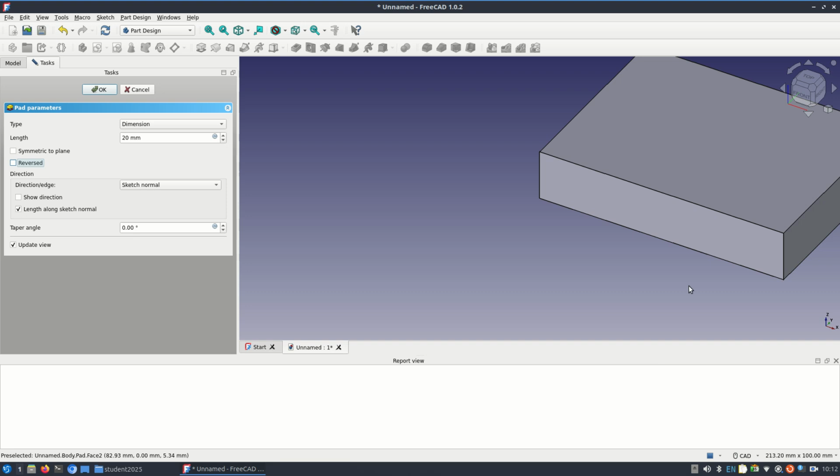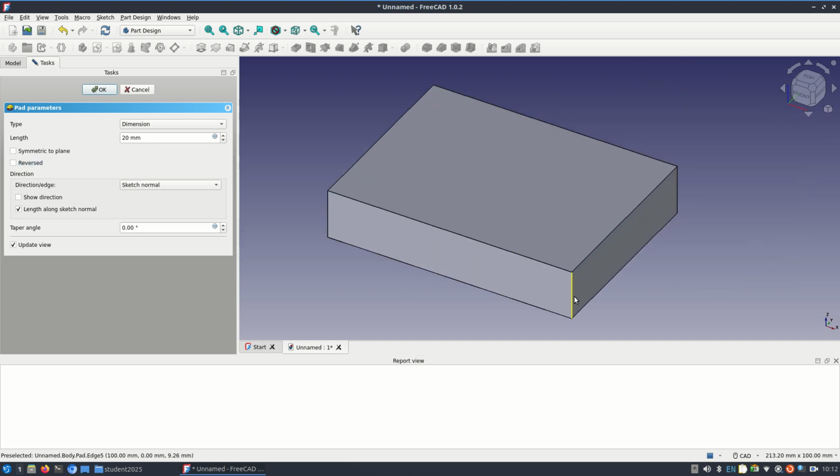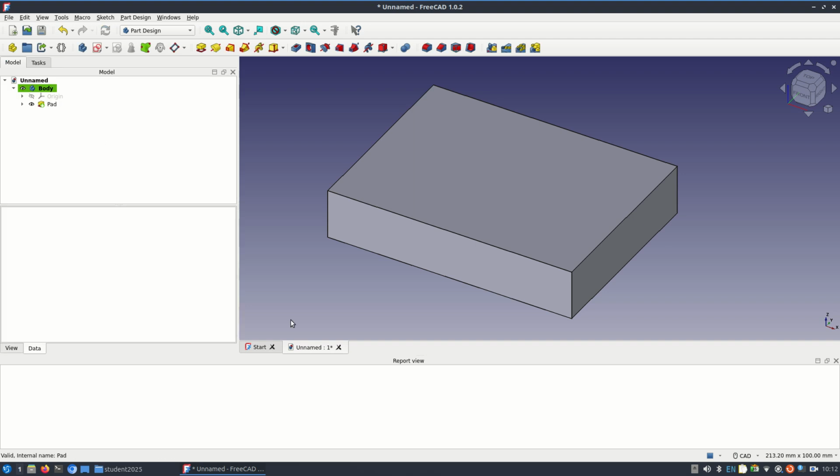So I measure my stock and I know that's 13, and then I just add a little bit more, right? Otherwise we risk cutting around and leaving a little bit of material there, so the piece is not going to cut off completely. So that's our first block.